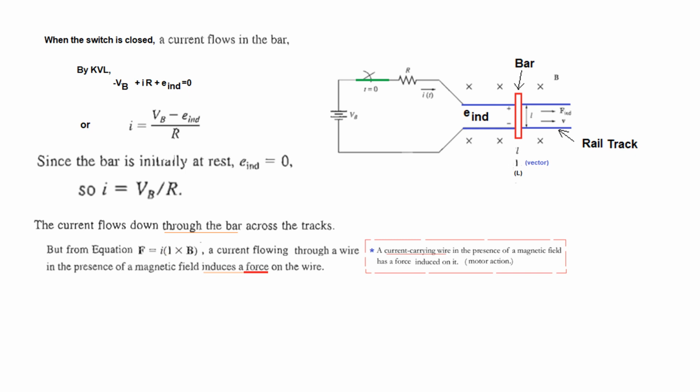Now there is a confusion here, and let's be clear. We are only concerned with the length from this portion to this, where the current is flowing, not the external portion. So this length is given by L, the magnitude is L. When we represent it as a vector in the direction of current flow, it should have been capital L, but Mr. Chapman has used this symbol, which apparently looks like a current I, but it is not current I, it is actually the length vector in this case. So we have to keep that in mind.